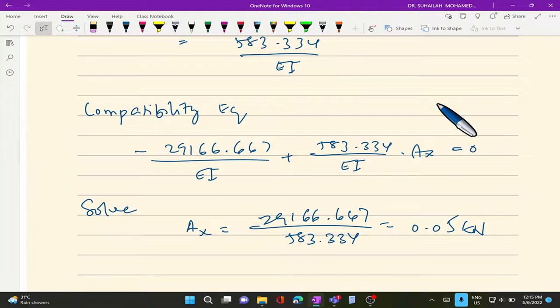So this is not the end of the analysis, but this is the procedure that we apply to all types of structure. Tak kisahlah beam ke, frame ke, truss ke, sama je proses. Except truss uses a different formula, because in truss we consider member forces as internal forces, unlike beam. For beam and frame we have to integrate the moment equation to get displacement.